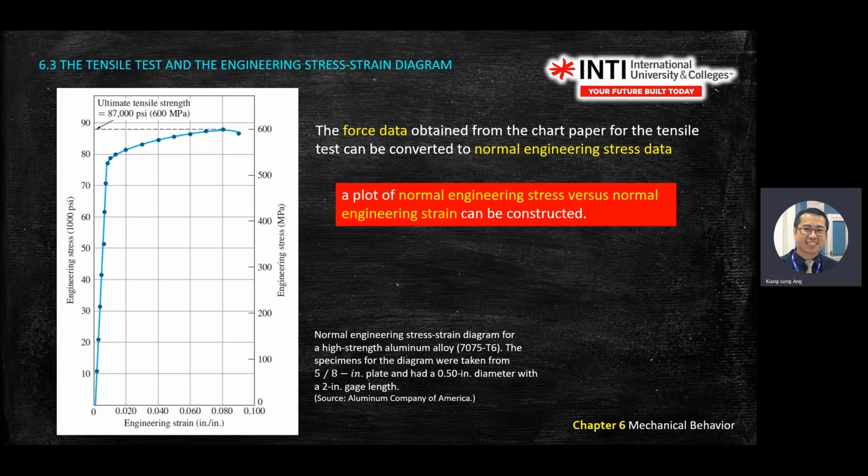So in your lab worksheet, you write number 1, number 2, number 3, and so on. Then you write measurement 1. You measure until it fails. For force 1, maybe 100 Newton. This is the force and the elongation, delta L. This is L1. It means you measure the original length, L0. Then you apply 100 Newton, and you measure the length. You get the first L1, and you have the force.